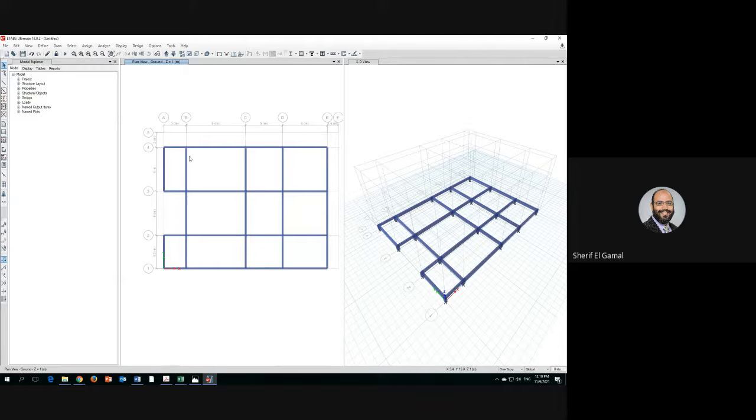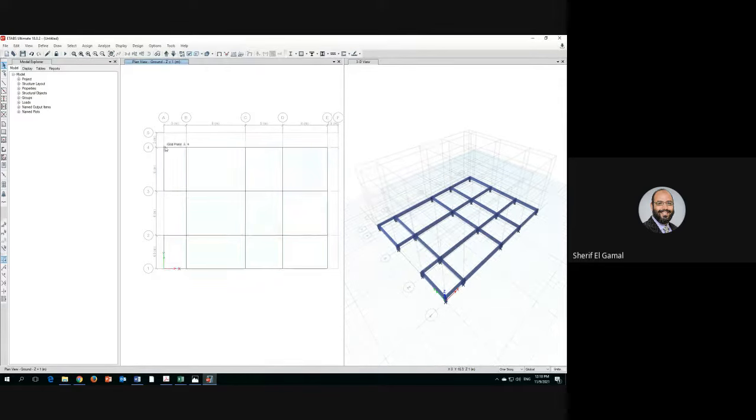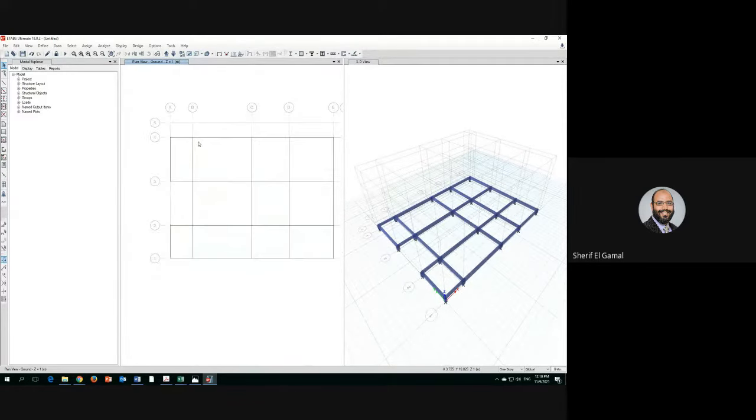Fine. If you don't want to see the extruded view, again, you can click on this one. It will be only lines. You can see the beams now are as lines. This symbol here, if you click, it will not cut the beam, but it will shrink the beams to show you which beams you have. You have this beam here, from this point to that point, shrunk just to show you that the beam is okay. And if you don't want the shrink, you can click again.